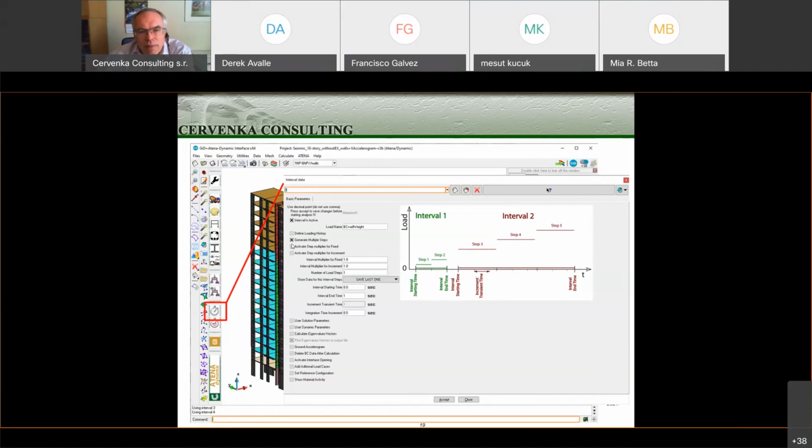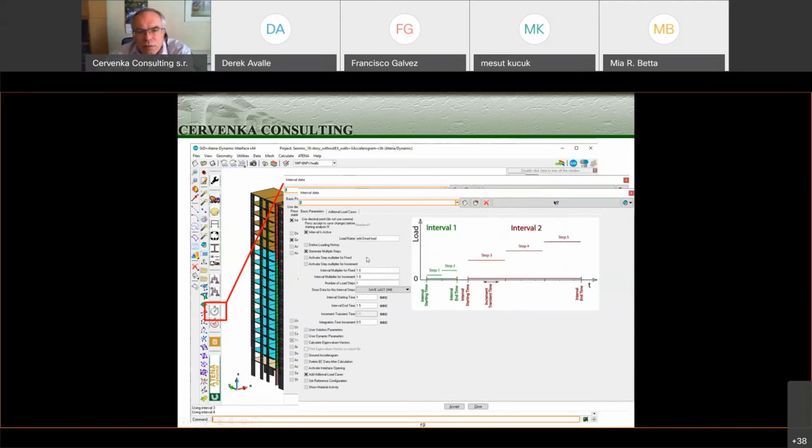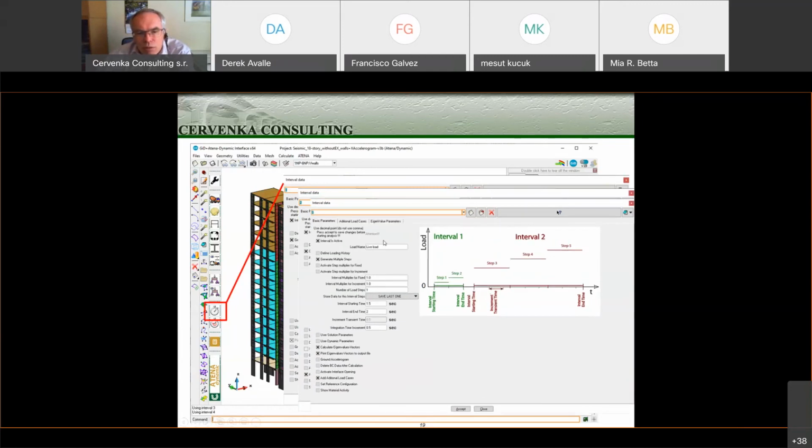In this case, we have to come up with some loading scenario. A typical loading scenario is that we first apply boundary conditions and self-weight of our structure. Then in the next interval, we add maybe some additional dead load for the structure. Then we apply live loads for the structure. We always have to define appropriate time, which, of course, should be somewhat longer because we want to be sure that we don't have any dynamic effects from this loading. So as you can see here, we are applying all these loads over several seconds.